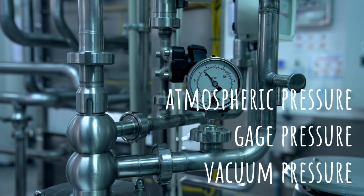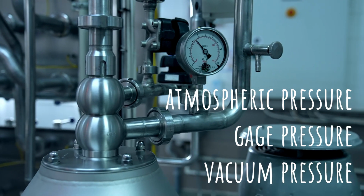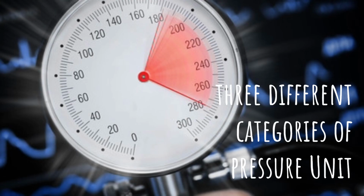In this video, we will learn the differences and links between atmospheric pressure, gauge pressure, and vacuum pressure. Pressure is defined as the magnitude of force exerted per unit of area, in the limit as this area shrinks to zero. This definition addresses the fact that pressure may vary in space in a flowing fluid. There are three different categories of units for pressure.